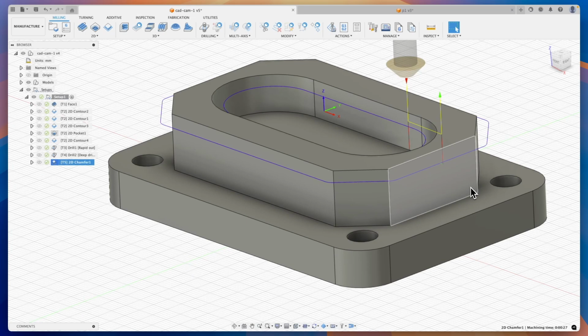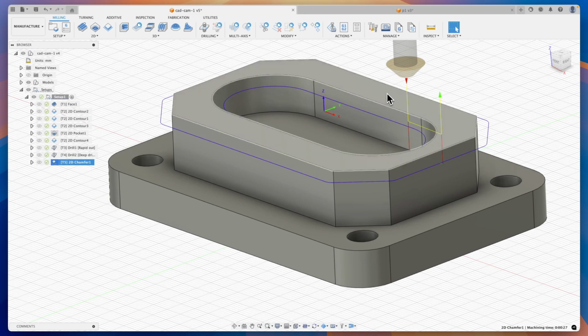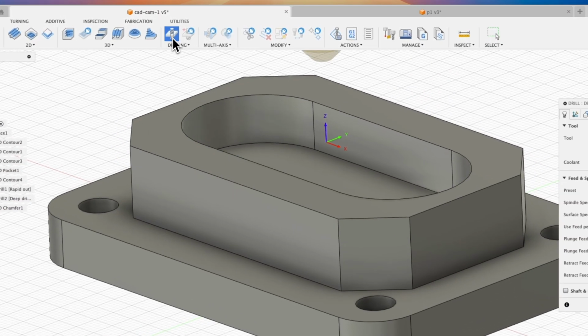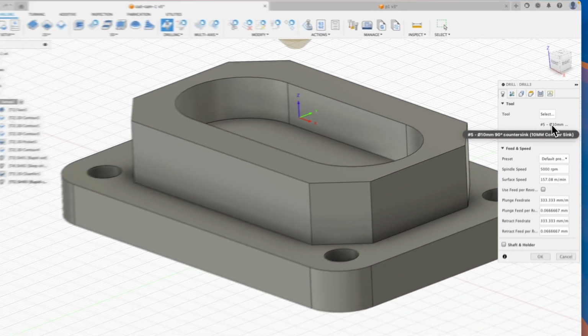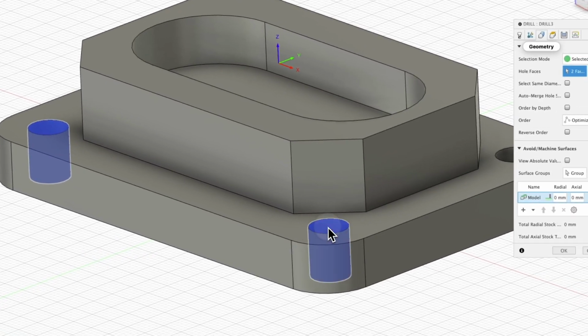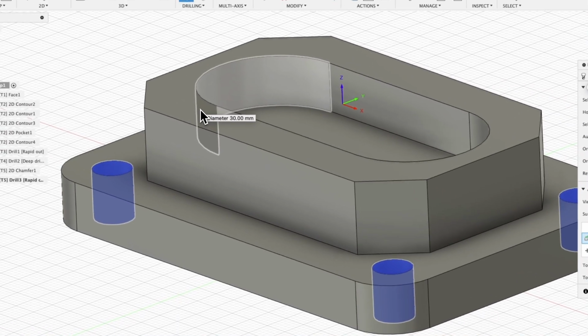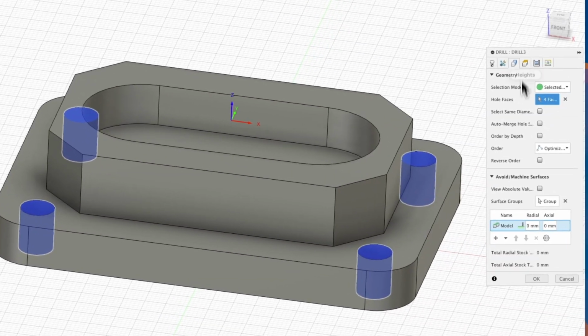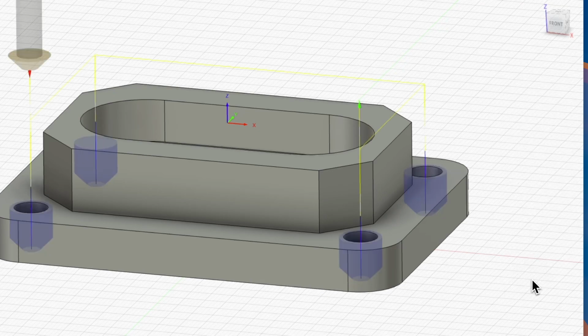And now we will proceed to perform the chamfer in the holes. We could also use this chamfering strategy here, but let's do it in such a way that we will use drilling strategy for this. We will simply add drilling to a specified depth to gently deburr the hole edge. I choose the drilling operation here. I leave this tool as the tool for machining and specify the hole geometry. Preparing the operation this way, it will simply be necessary to specify the drilling depth. Let's calculate this with the default parameters. I click OK, and it looks wrong.